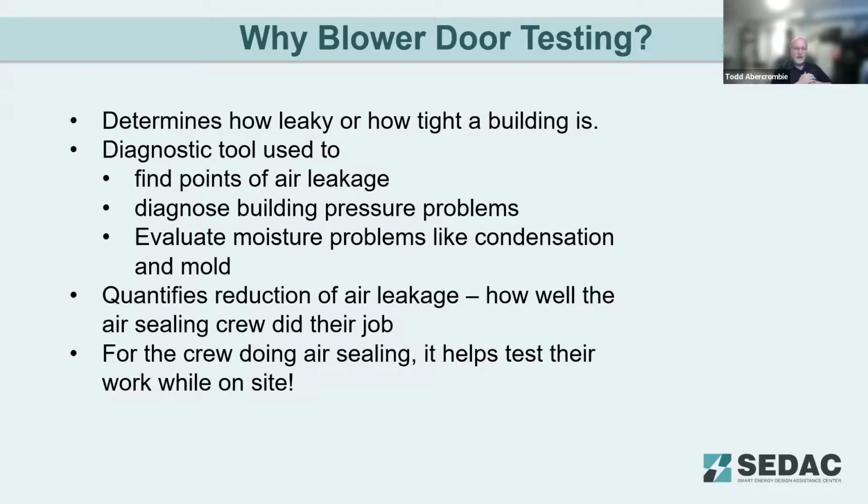It can diagnose building pressure problems as well. Some areas have more pressure than others. You can evaluate moisture problems like condensation and mold by understanding the tightness of the building and its connection to the attics and crawl spaces and other areas.